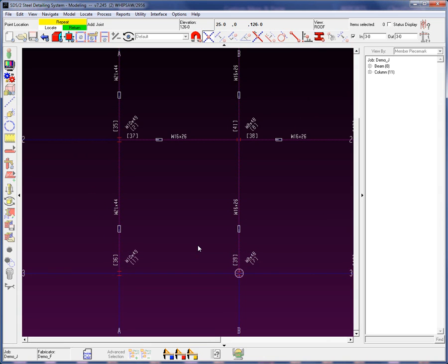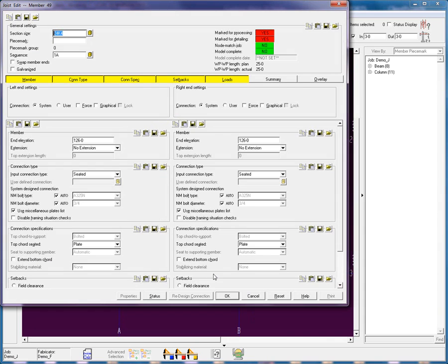So when we put in a joist, even after process, we are not going to have any solid material unless you run a parametric that'll place in solids for the chords and for the diagonals, but these are of course just a representation. Or if we bring in what's called a BIM joist, which will be the accurate representation of the joist from the joist manufacturer. So I'm going to go ahead and add in my joist using intersection construction line. I'm going to type in here 24K4 joists. We can see our elevation at the top of my joist is at 126.0.